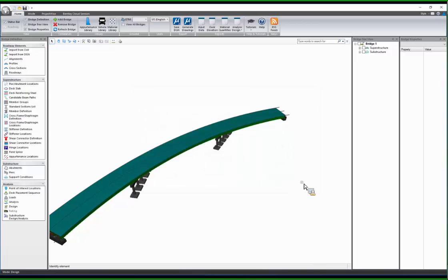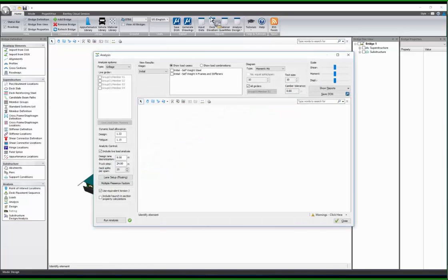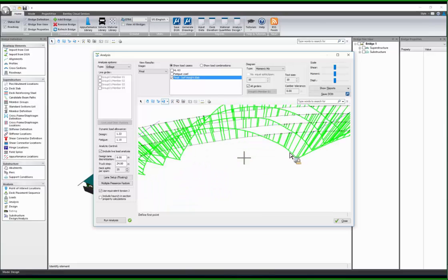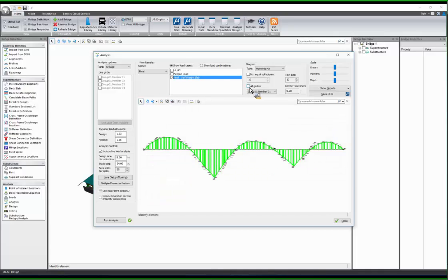One of the reasons, of course, it takes some time, that's fine, but the reason that I brought this for us is this. If I go to the analysis, remember, I already pre-analyzed this particular bridge. But what I'm interested in showing you is this. How do I use the product? At least one of the options is to go into my final, okay? You can see the moment diagram already. You definitely will realize where the inflection points are, okay? But I want to simply define one of them, okay? One of the girders. Look, and I can select whatever girder that I want to work with.